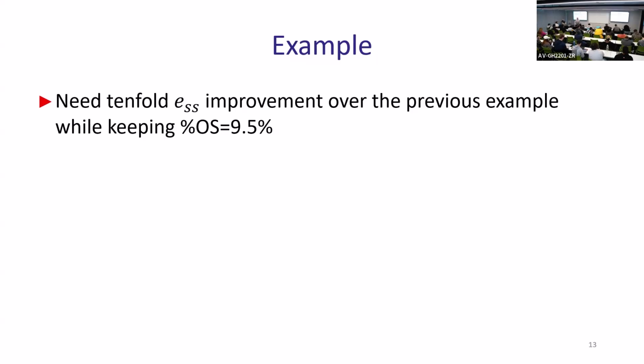steady state error, right? And since you have an integrator in the loop, to a step response you don't have any steady state error. The steady state error is 0 also because you have an integrator in the loop. So you can talk only about KV and not KP here. So you want to improve KP, but there's nothing to improve. It's perfect. Now you're improving KV 10 times. And this means that your gain needs to grow 10 times.